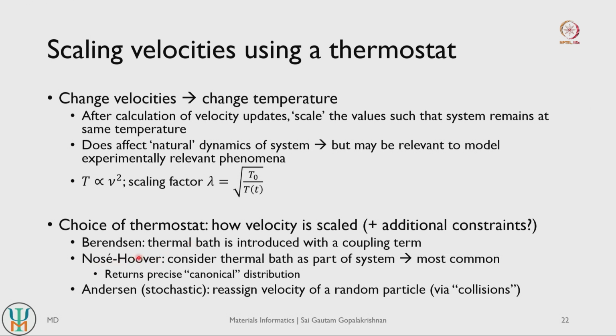The Nosé-Hoover thermostat basically extended this Berendsen thermostat, but it considered the thermal bath to also be a part of the system. In Berendsen, your system is separate, your thermal bath is separate. So think of your system and your thermal bath as system and surroundings, right? The thermal bath is still an external entity. But there are computational reasons why that is not the most efficient way to scale velocities. So in Nosé-Hoover, you actually consider the thermal bath to also be part of your system.